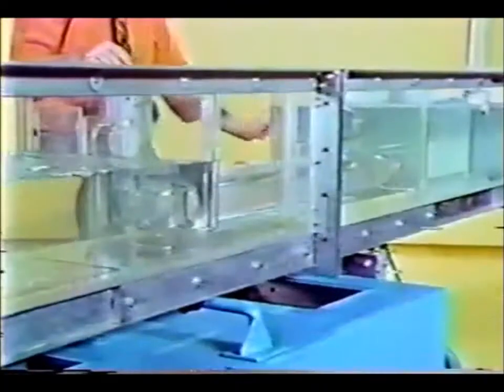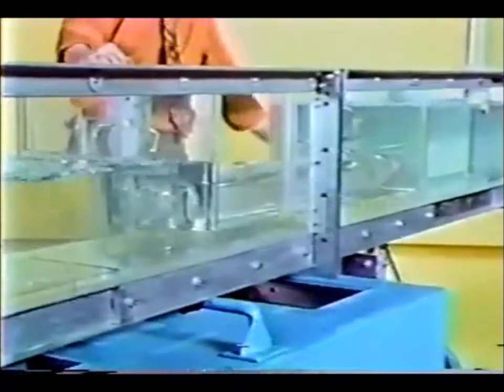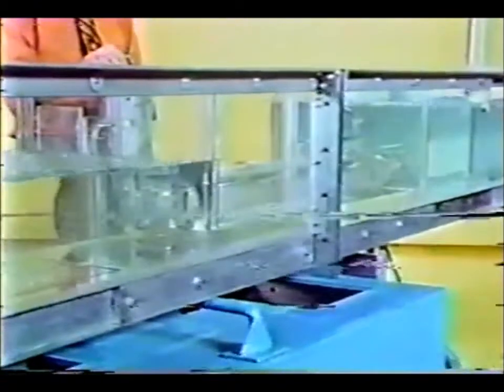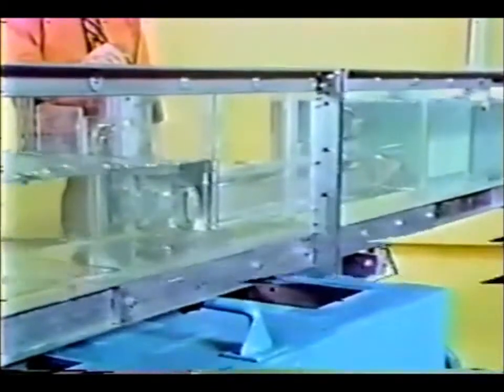Next, let's look at the factors that influence headwater elevation for inlet control. In inlet control, free surface flow exists throughout the culvert barrel. To show inlet control in the model, we will tilt the flume to increase the culvert slope. Notice that the tilt axis is near the outlet invert. If you watch the headwater, you will see that it remains at the same level as the flume is tilted.